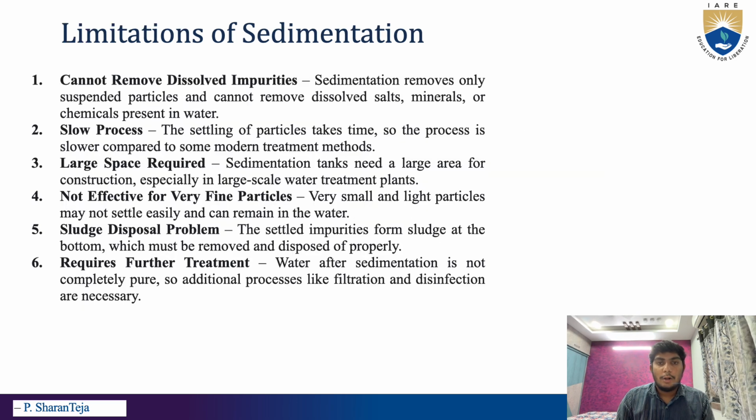Limitations. Although sedimentation is useful, it also has limitations. It cannot remove dissolved impurities, it is a slow process, and it requires large space, meaning big tanks are needed. Fine particles may remain. Very fine particles do not settle easily. Sludge disposal is a problem and additional treatment is required, as the water is not fully pure. So filtration and disinfection are still needed. So sedimentation alone is not enough.